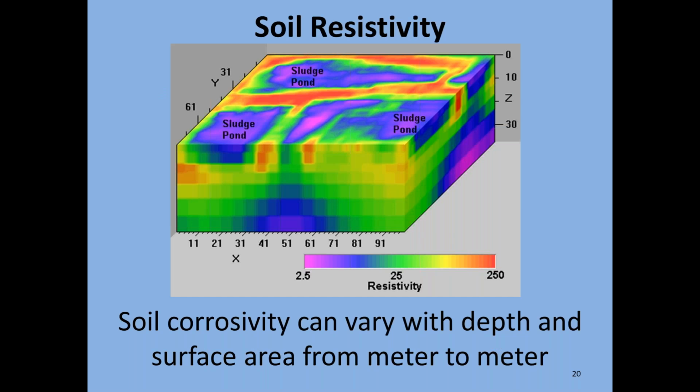We always recommend to test a soil sample every acre in a grid pattern, so that if you do end up with a hot spot, you can just knock out that grid as being the hot spot, and you are confident that the rest of your site is not super corrosive. If you just collect 2 random samples from a 20-acre site, you're going to have to go with the worst results, because you can't take any chances for liability.